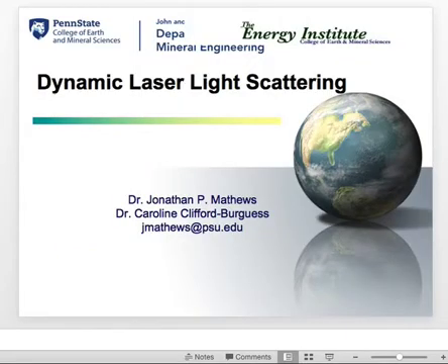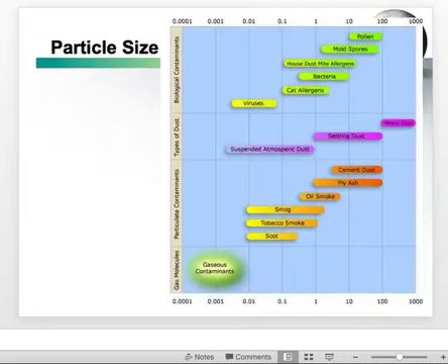So moving on to laser light scattering. We have a range of particle sizes on the smaller side that we're interested in. Obviously at the top we've got things like pollen and mold and allergens and bacteria and things of that nature. And you can see here the scale is on a log basis. You've got heavy dust. Dust, I'm not really aware of an official definition. We've always used 100 microns in dust research for mine ventilation at Penn State. So it's particles smaller than 100 microns.